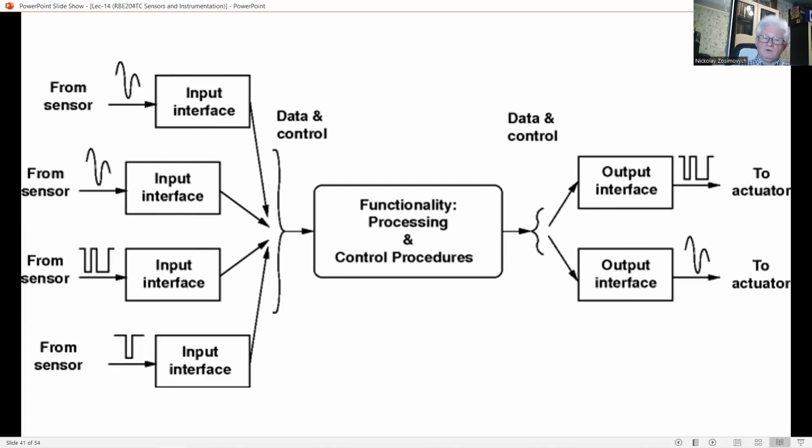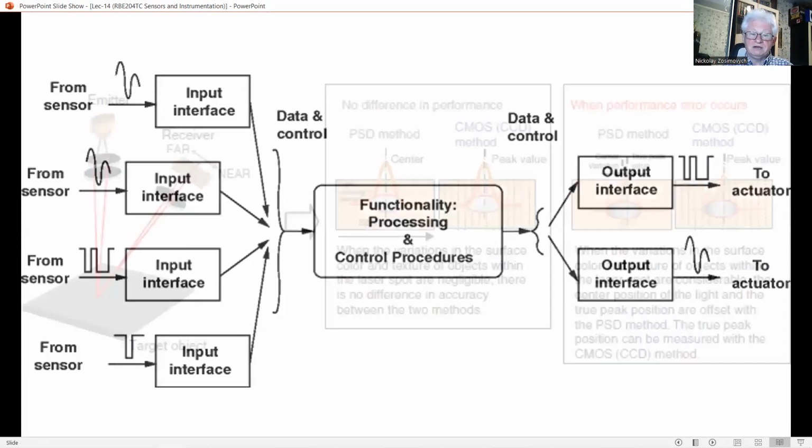Digital flow control may be accomplished using a digital control valve. A typical digital valve consists of a bank of orifices, each sized in proportion to a place value of a binary word. Each orifice is actuated by a separate rapid-acting on-off solenoid. In this manner, many combinations of discrete flow values can be obtained.